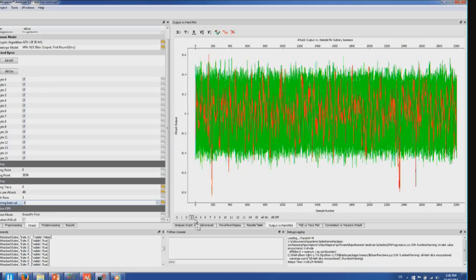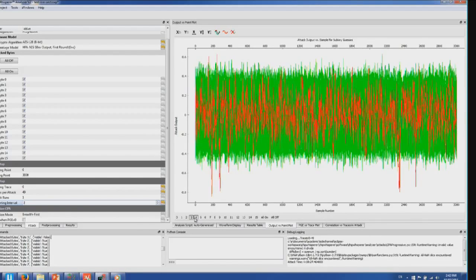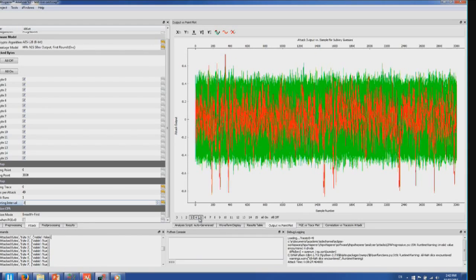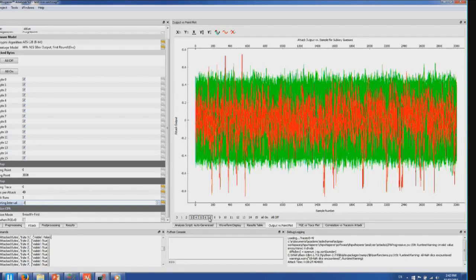When I run the algorithm, you see this big spike, and this is for recovering byte number 3 of AES. If I say, okay, where did you recover byte 4, you'll notice this other red spike at the next point in time. In this case, there's just a for loop in AES doing each of those XORs and SBox lookups, and you can see the offset of how long it's taking to run through that loop. So you don't really need to know exactly where the AES itself is happening. The algorithm will pull that information out for you.